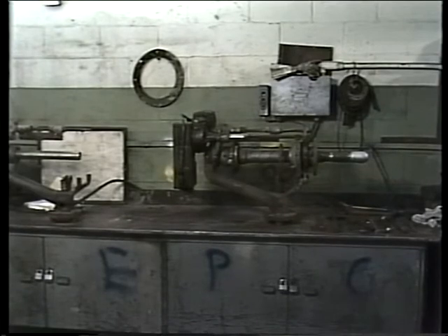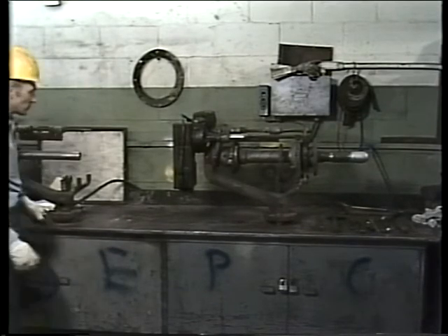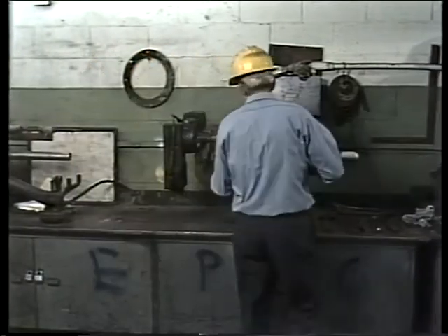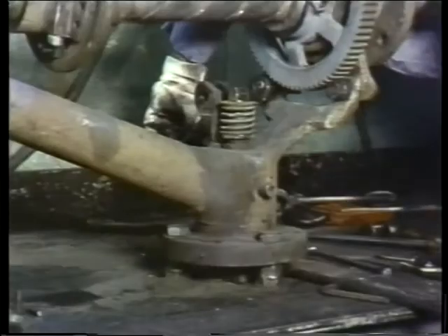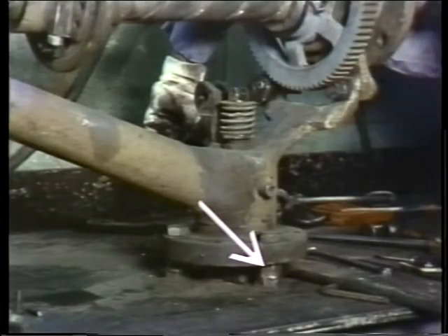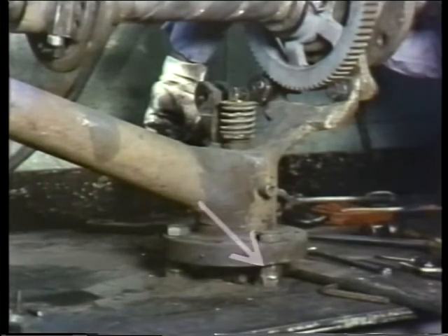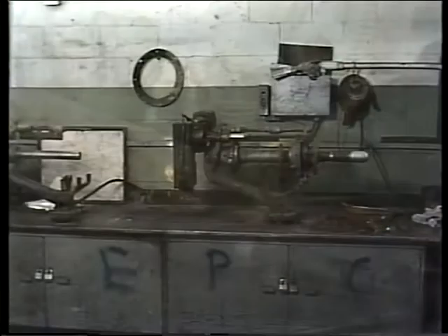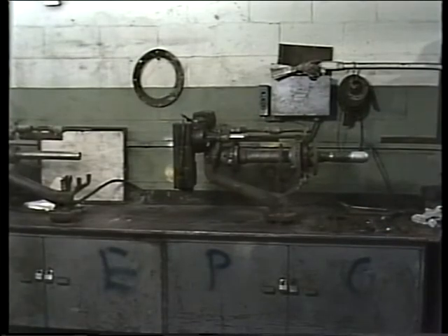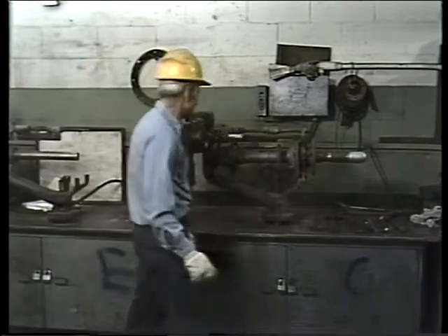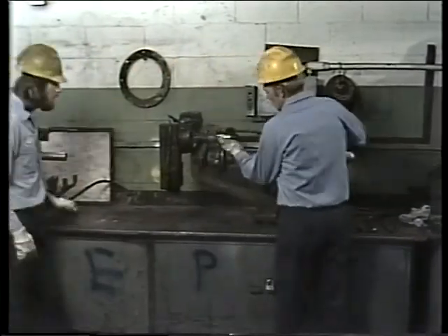The smaller soot blower we're using for our example here can be pretty easily put up on the bench for its maintenance. The mechanics have rigged a fixture to the bench so the blower can be bolted down while it's being worked on. Here, they've already removed the protective shroud over the main drive gears. The next step is to pull off the motor drive assembly.